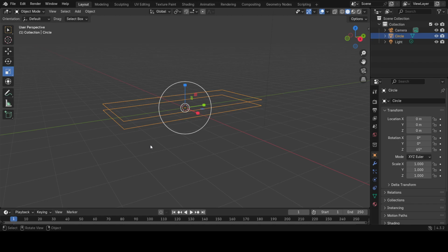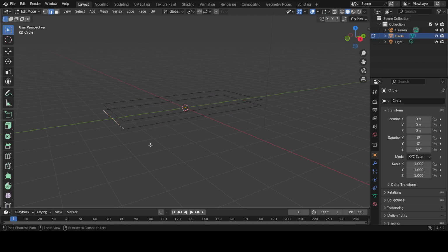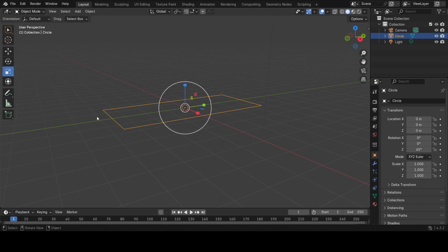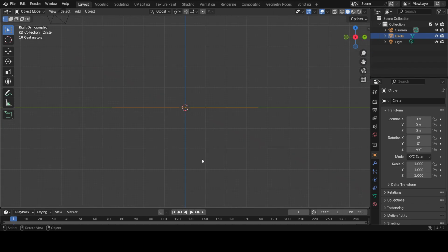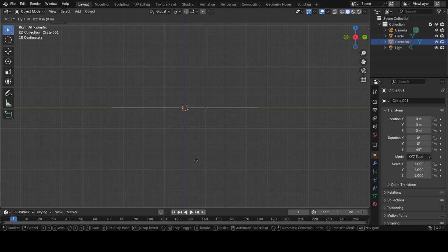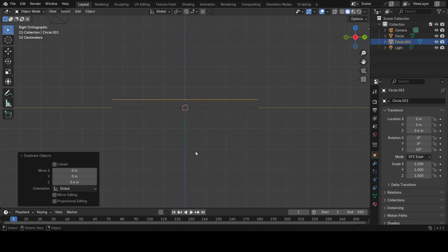Okay? So let's go back here one more time. I'm using Control Z to undo. This time let's go to the object mode, and again, X, Shift D as in duplicate, hold down Control, and then move this up just ever so slightly like this in one direction.